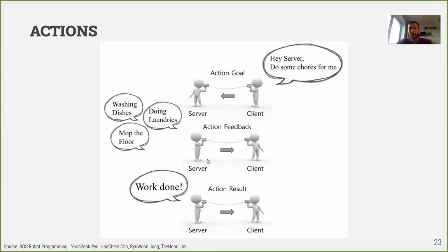It is not quite that popular in ROS. It exists. It is used many times, especially with industrial robots. For example, you ask a robot to reach some particular pose, and it takes some time. And in this case, actions is a good mechanism, because you can send the request to reach some pose. Meanwhile, you can continue some useful calculations, some planning, or so on. And then once the goal is reached, you get the feedback that the goal is reached, and you can, for example, plan a new trajectory or something like that. So it finds application in such cases.